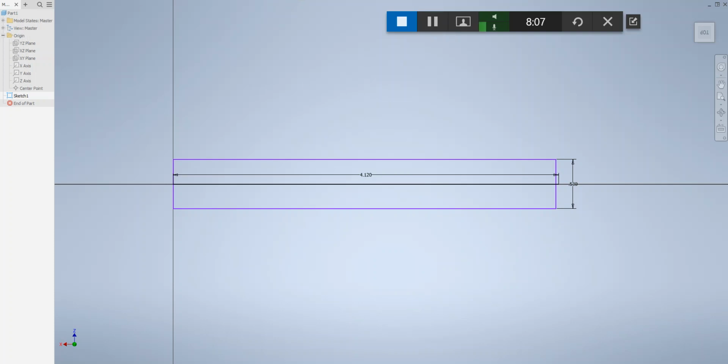Okay, so the fillet over here, and the size of the fillet is important. I want to set it to 0.25. So I'm typing 0.25, and then I'm going to select top corner and right corner, top corner and bottom corner. Okay, so this is the handle, and now it doesn't have any sharp corners.